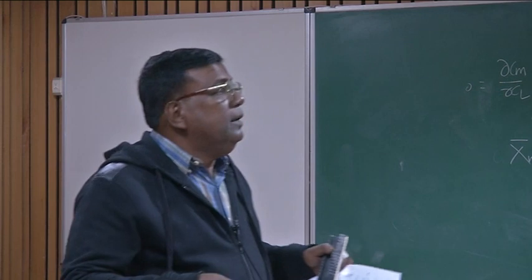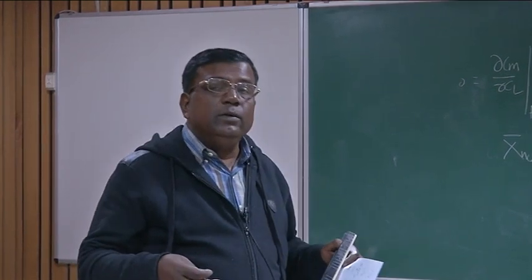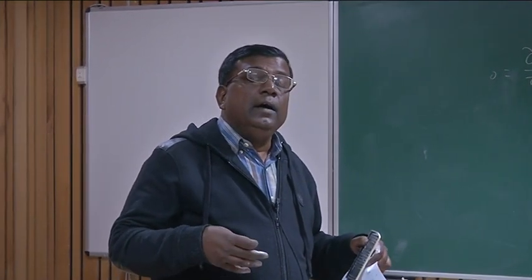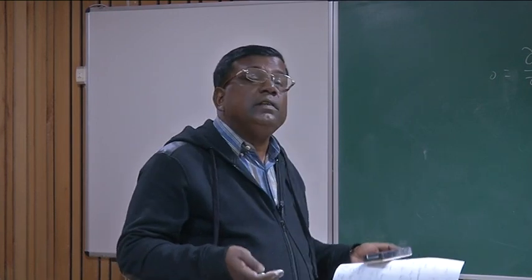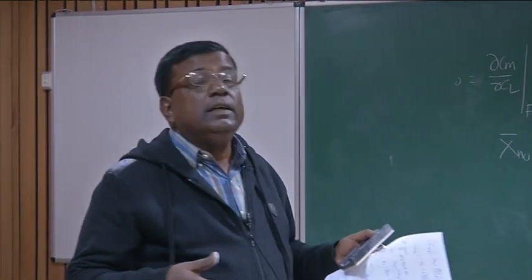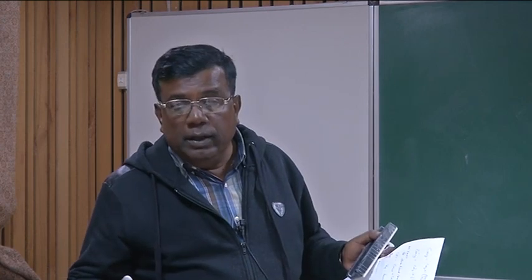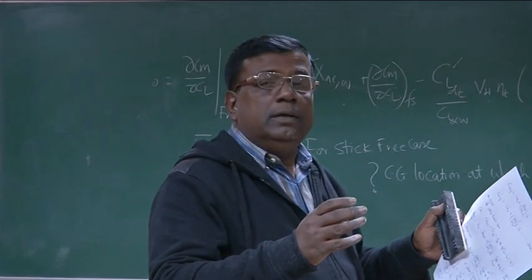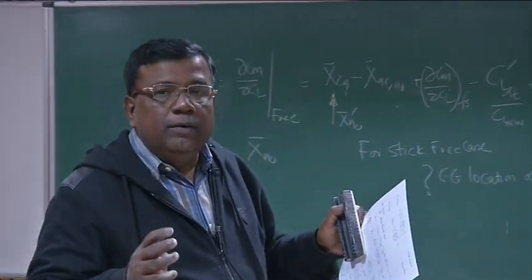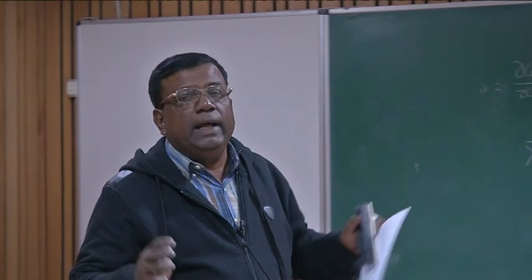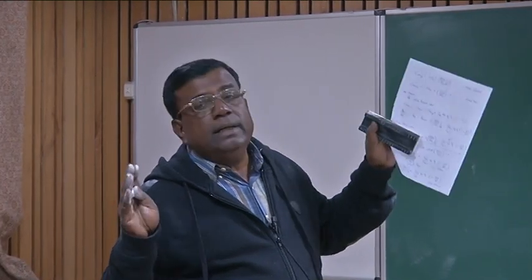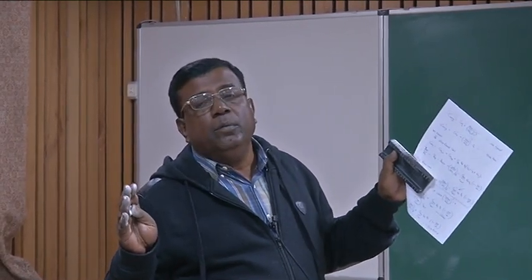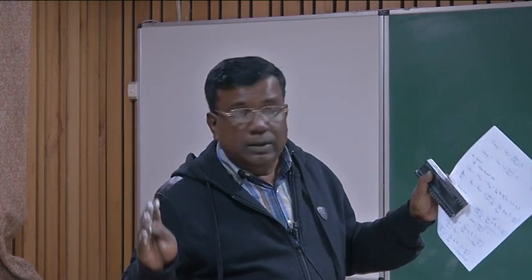Second thing is, in a stick free case, what we are trying to do is develop the background to model stick force, how much stick force is required. In the stick fixed case, what we are answering is how much delta E is required. So this is a subtle difference in the modeling. In the stick fixed case, our focus is on how much delta E is required to fly at a particular CL, governed by delta E equal to delta E naught plus d delta E by dCL into CL trim.